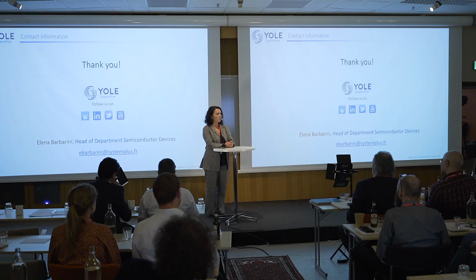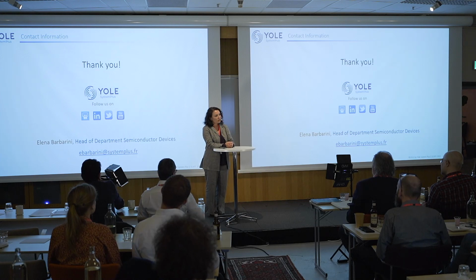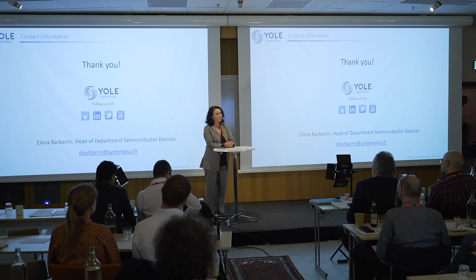Then the problem is the reliability of that device and its strength at high temperature, if you compare with silicon carbide. The advantage of going to silicon carbide is also to keep higher temperature in the traction inverters. And then what's the interest of going to high frequencies in the traction inverter? That's also a question to consider. So for me, it's a nice exercise for them to show the capability to go to this voltage.